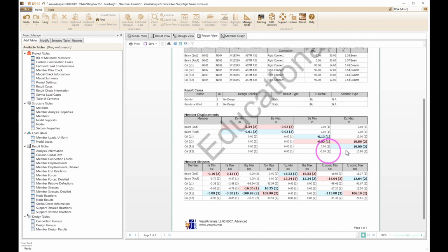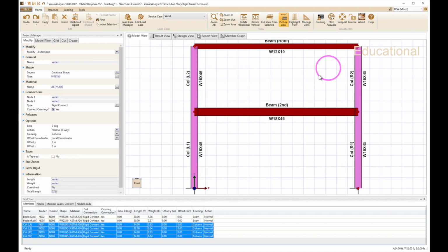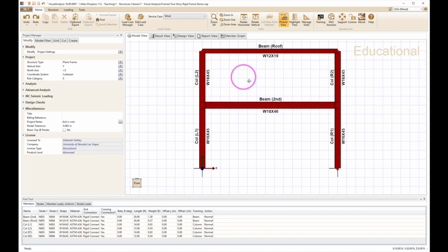We're going to need a lot bigger member. And look at the stresses here. That column is up to 113 KSI. So you have to play around a lot to make that a good structure. So generally speaking, we want to avoid the minor axis bending unless there is some other overriding concern. So let's turn those back.